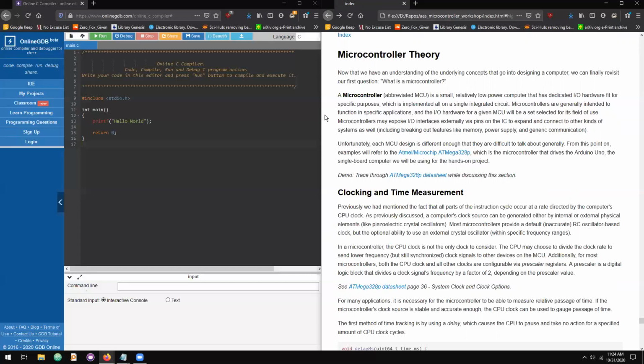So remember, for an integrated circuit, you have signal terminals at the edge of the physical device that are called pins, and those carry our digital, or in some cases, analog signals. And the pins that are exposed on microcontrollers are usually used as the external interfaces for hardware I/O, or as a means of attaching other external electronics, like external memory and external clock, features like this.